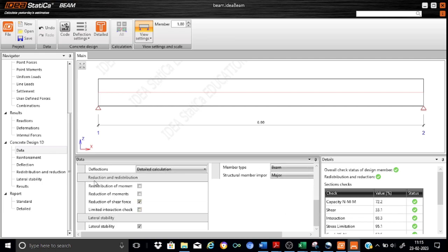And if you look into the reduction of the shear distribution, I have only asked for a reduction of the shear force. So if you go through EC2, you'll find that it prescribes that the shear verifications need not be done for sections which are closer to the supports than d, right? So accordingly, the shear force needs to be calculated only at the effective depth d from the face of the support, and then the corresponding shear verifications need to be done.